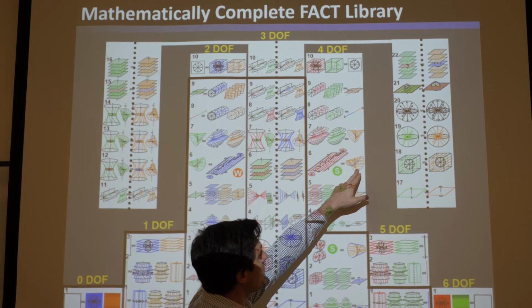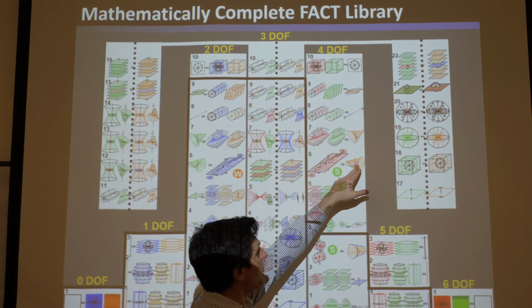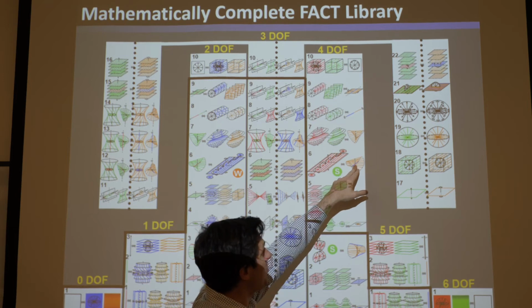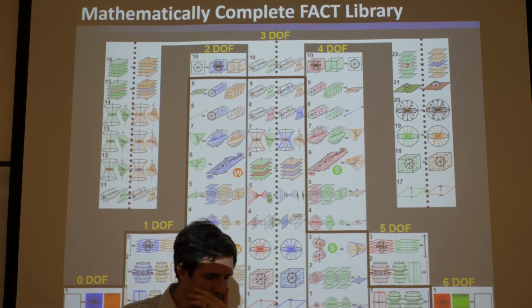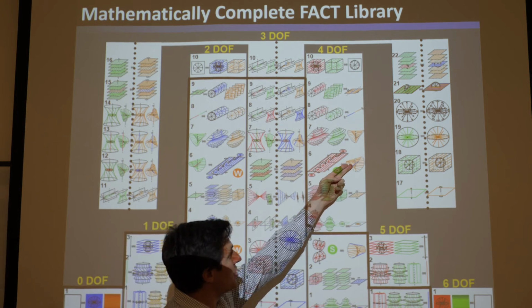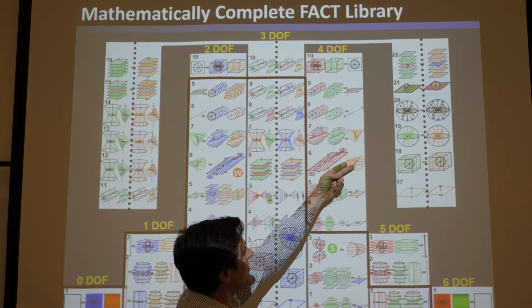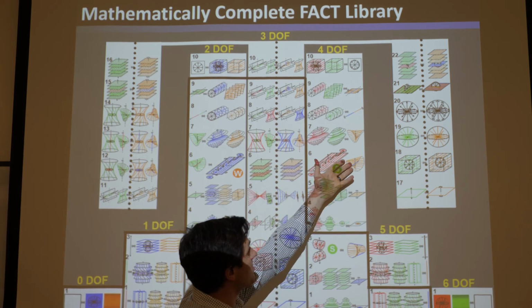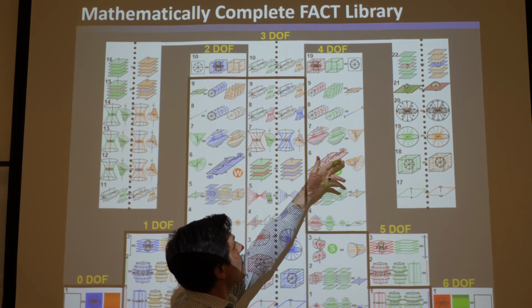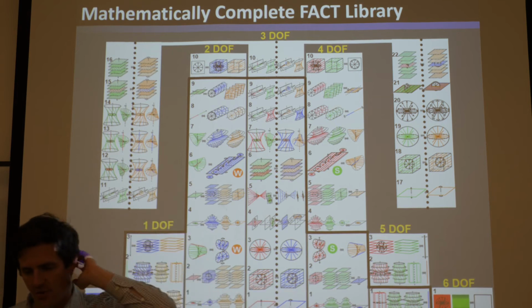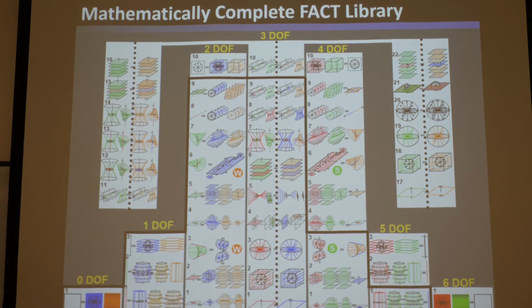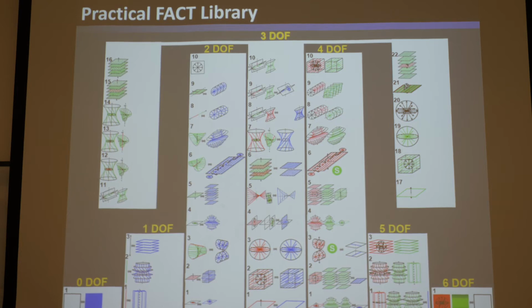See, this is a cylindroid where its principal axis only has 1 blue line and the rest are orange. Since there's only 1 blue line in there, even though blue lines are useful, we can't use this constraint space to design flexures because it needs at least 2 to satisfy 6 minus 4 equals 2. So what we're going to do is get rid of all the orange lines, all the black moments, and any constraint space that has fewer blue lines than 6 minus the number of degrees of freedom. If we do that, we get something like this.